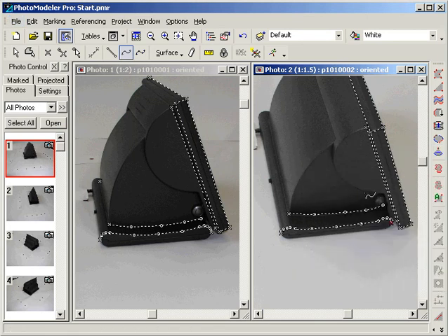We will model the base with two separate curves. We could have modeled it with one closed curve, but we have better surfacing options when using two disjoint curves rather than one closed curve. With a single closed surface, the only surfacing option is to use path mode. The loft surface mode can be used with the two curves, and it offers a more accurate NURBS form.